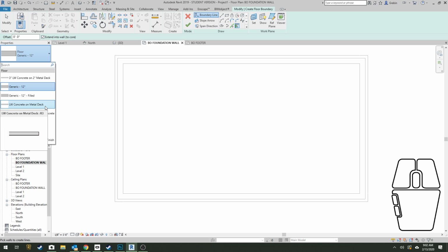That's a commercial floor for floors of buildings above the first floor that use a special metal decking system. That's nothing we've talked about yet. Steel bar joist VCT on concrete. That's again a commercial floor we've not talked about yet. And then this is 3-inch lightweight concrete on 2-inch metal deck. That's a heavier duty metal decking and concrete floor, composite floor, again for commercial buildings.